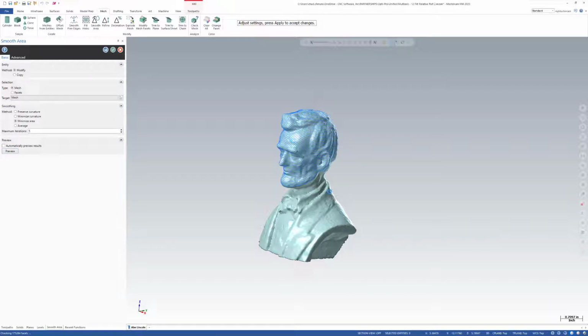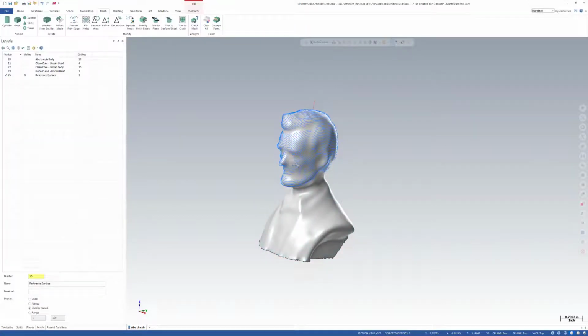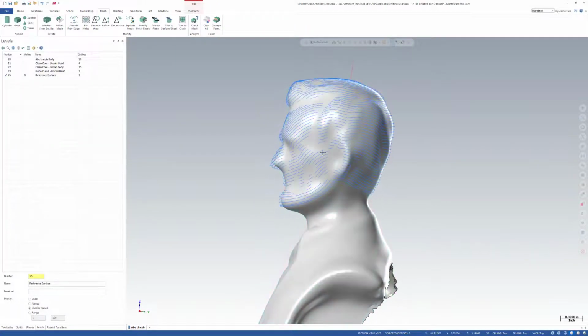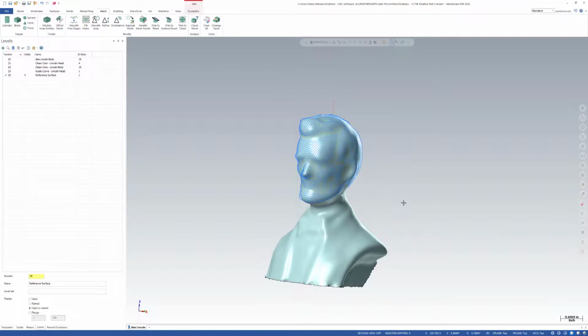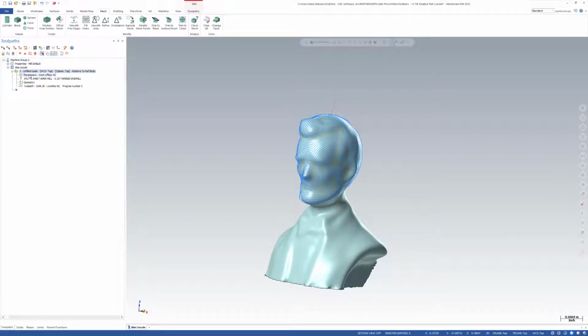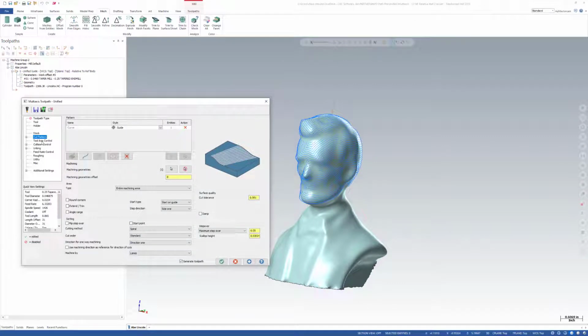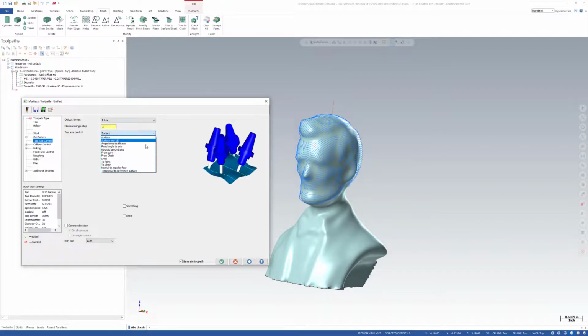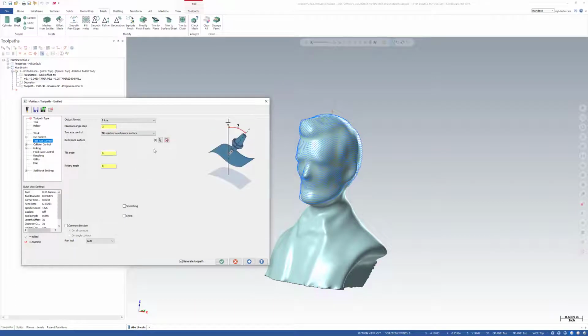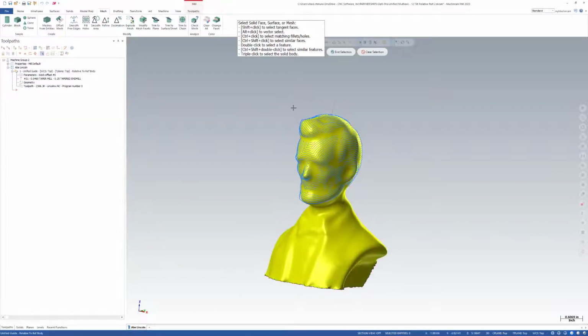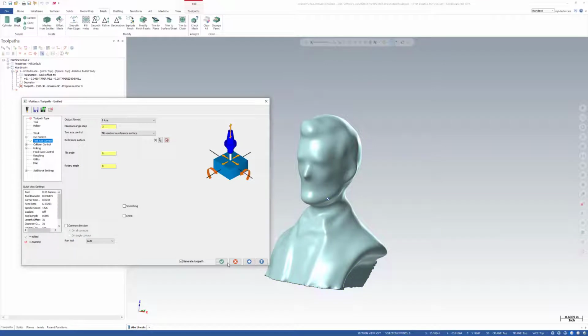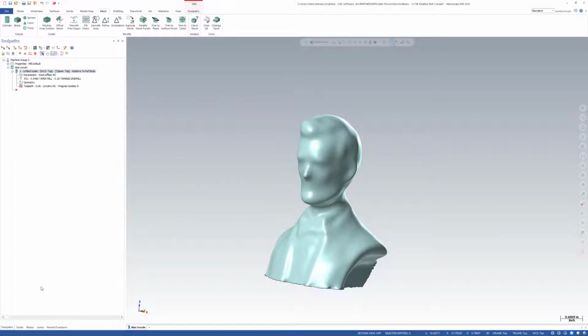It should turn into kind of a blob. But we remove a lot of the detail, right? So using this as tool axis control should give us something much nicer. So let's go in here and say tool axis control based on reference surface, that being this one, and generate this.